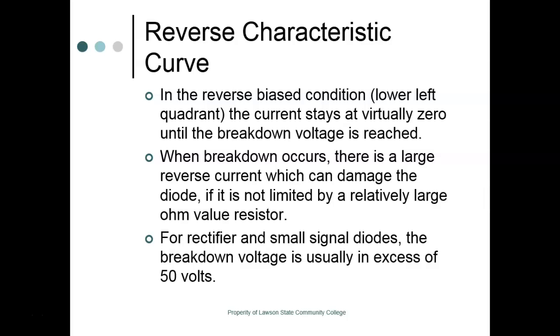We'll do this as a team, because we're going to deliberately break a diode over in the reverse direction. But we're going to have a 10 mega ohm resistor in series with it. So when it breaks over, we can see the current increase through the resistor by measuring the voltage drop, right? You understand that? And we'll actually see it break over. I think our diode breaks over at around 90 volts. So that's above lethal, so we need to know that, right?